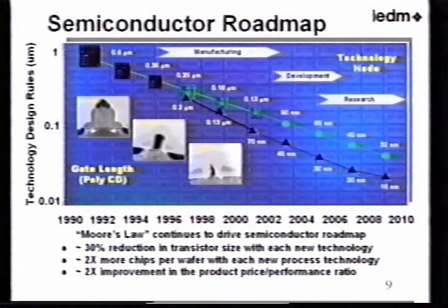So for example, a 130 nanometer technology node is not manufacturing devices that are running with smallest details of 130 nanometers. They're really running with channel lengths of about 70 nanometers, so considerably smaller. And we expect to see this trend continue. What you're really seeing is an acceleration over several technologies, as we've seen the deviation between what the smallest physical geometry is and what the effective channel length that we are seeing in those logic devices.